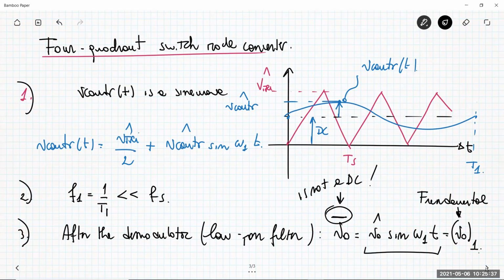Basically, this process starts from a pulse width modulator that converts information in the variation of an analog signal into the variation of the width of a rectangular signal, so the pulse width modulation, and then it's amplified and filtered out to obtain the variation you had at the beginning.